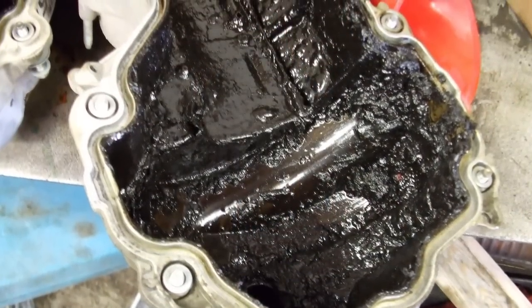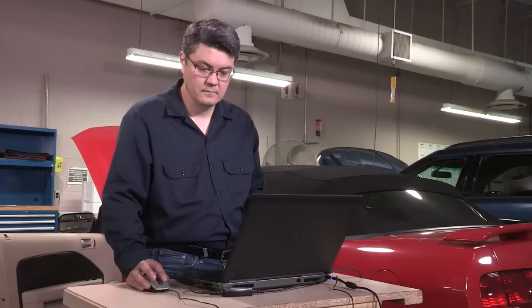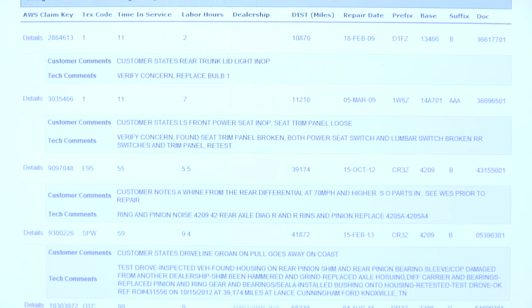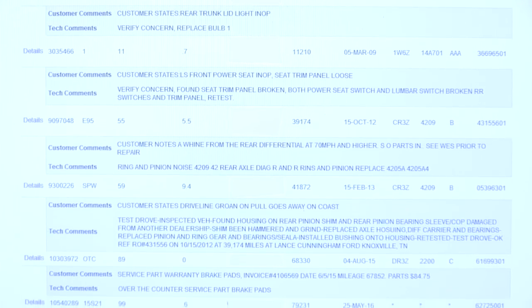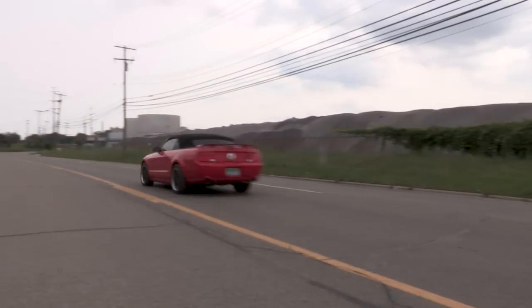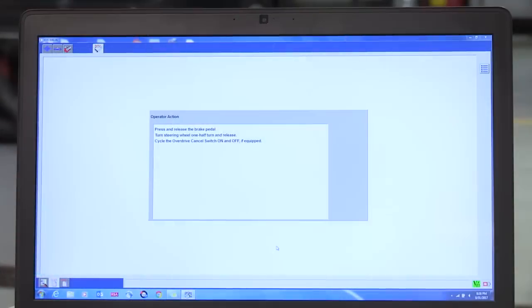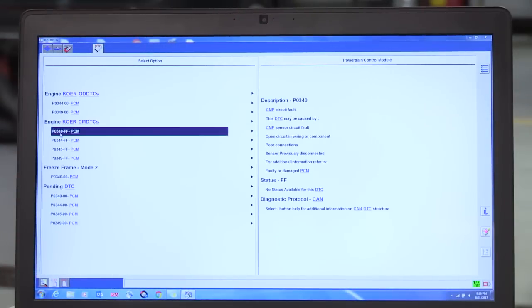If lack of maintenance isn't the problem, check the maintenance history, especially the warranty and repair history, for signs of recurring drivability issues. Then, it's time to perform some preliminary diagnostic steps to see if any VCT issues might be causing the customer's concern.